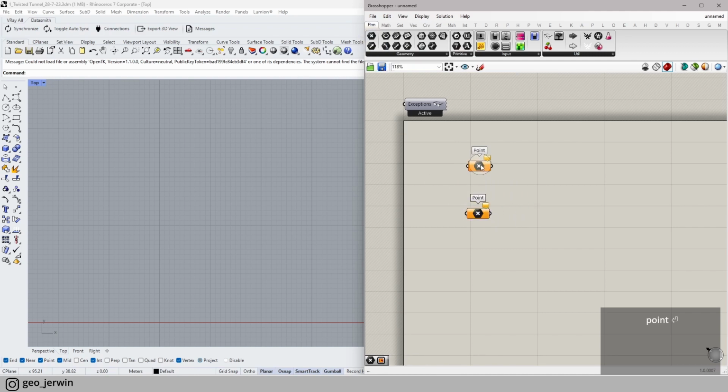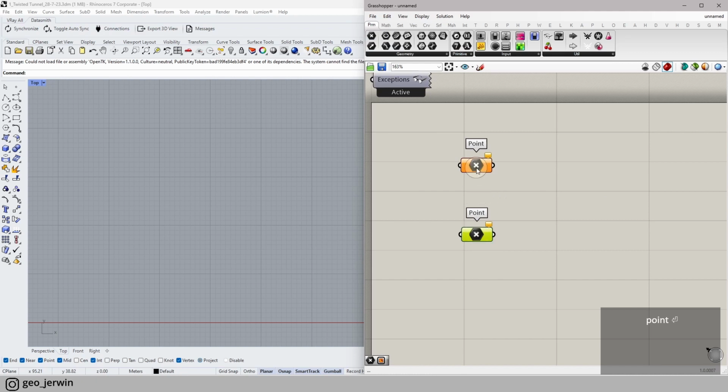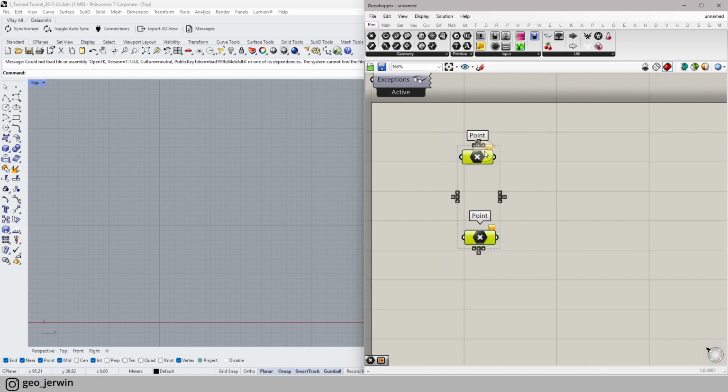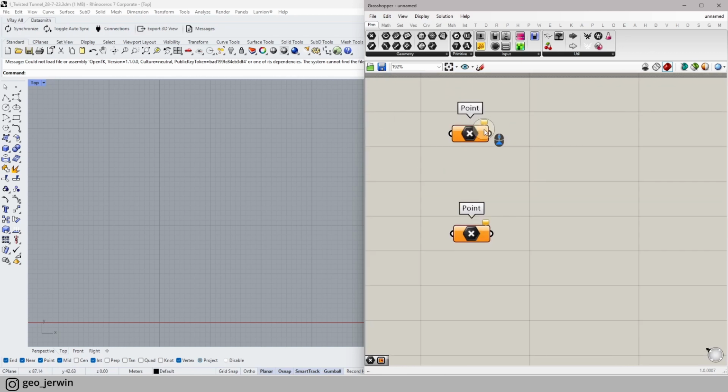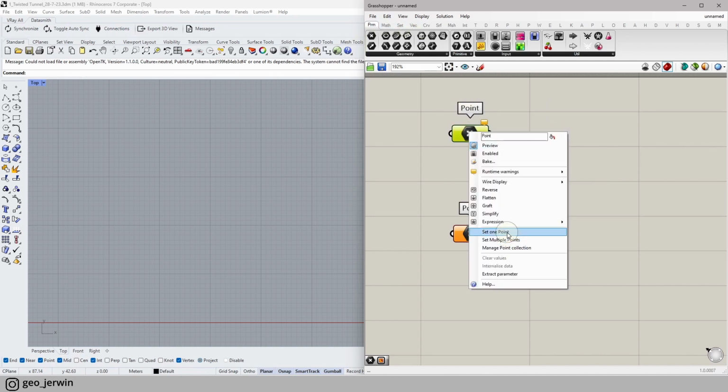All of these hexagonal and single-component looking things are basically called floaters, or it could be like a container for any sort of object. So this is a point container, so it can contain only points. And as we know, this is orange, so it lacks data. So we have to set data manually. When it's an orange container, like these hexagonal objects, we have to set it manually. We cannot create it from scratch usually. So you'll understand it a bit more when we move on. You can construct a point as well. I'll tell you how. So here's a point.